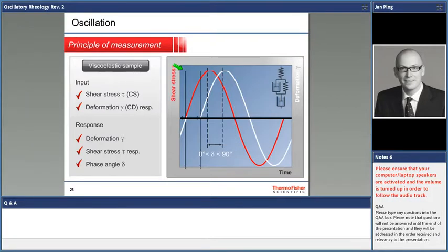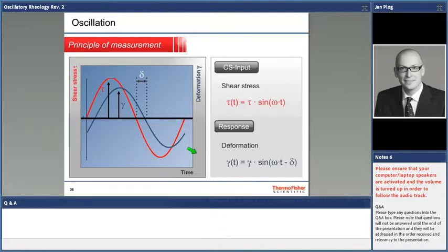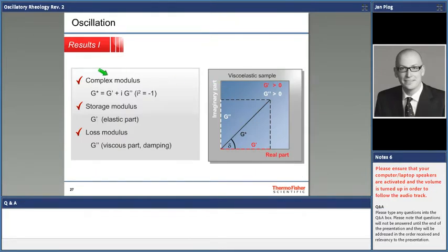However, again, in reality we are somewhere in between. We have viscoelastic fluids, with some viscous components and some elastic components to it. When you do the same test, this phase shift, the phase angle, will thus be somewhere in between pure elastic behavior and pure viscous behavior. This is what you measure. So let's not talk about wave math too much here. I also don't want to run out of the agenda.